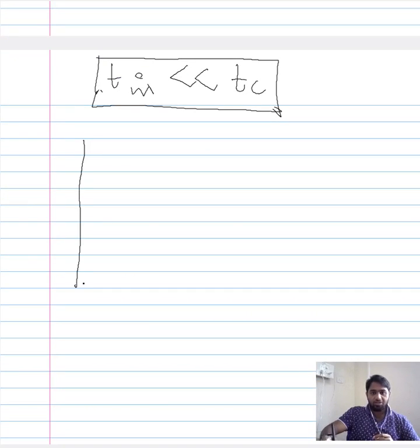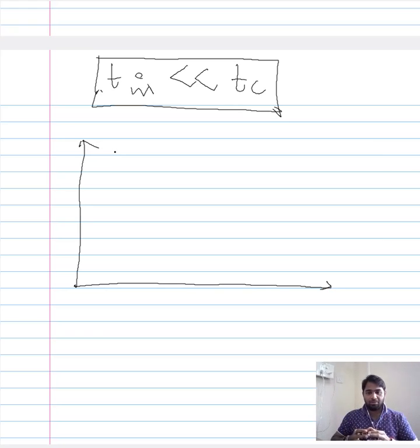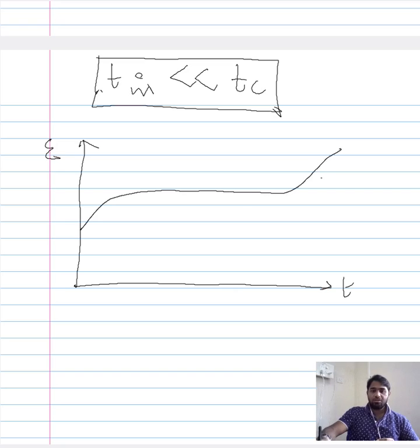When in a crystalline system, the duration taken for the instantaneous creep is insignificant when you compare it to the overall creep period, then it becomes rather difficult for us to express it in terms of this curve. So the curve begins with the transient region and follows with the steady state region and ultimately the accelerating creep region.